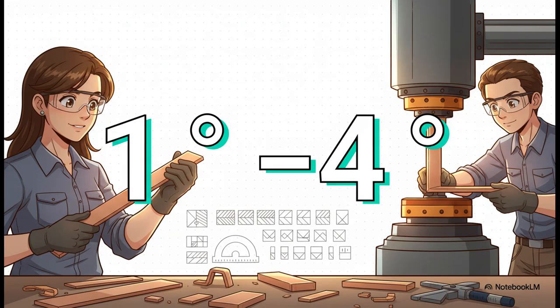To compensate for this elastic recovery, seasoned fabricators use what's called an overbend. They'll actually bend the copper slightly past your intended angle, usually somewhere between 1 and 4 degrees, depending entirely on the temper. Soft copper, it might only need 1 degree, but hard-drawn copper might need up to 4. The only way to know for absolutely sure is empirical humility. You have to fine-tune the exact angle with a sample piece of scrap copper before running the final production parts.